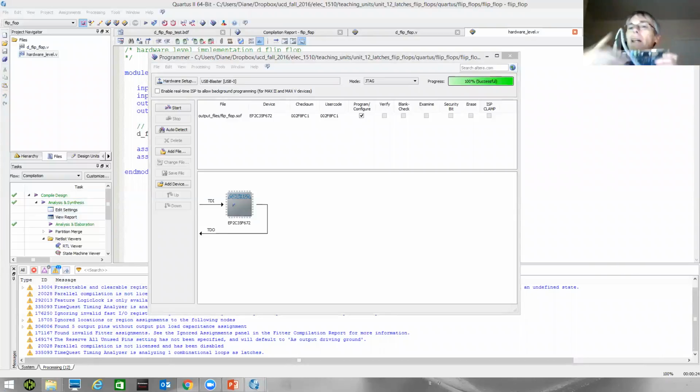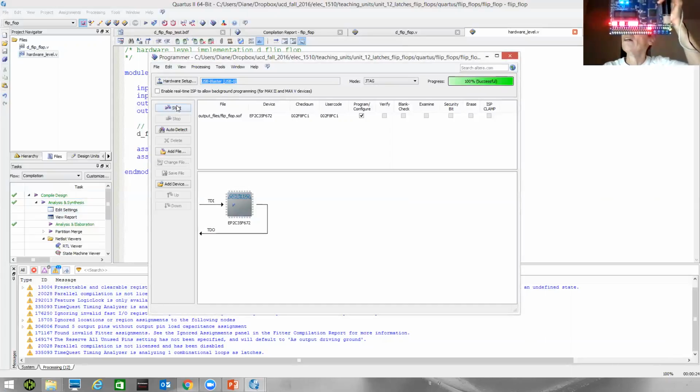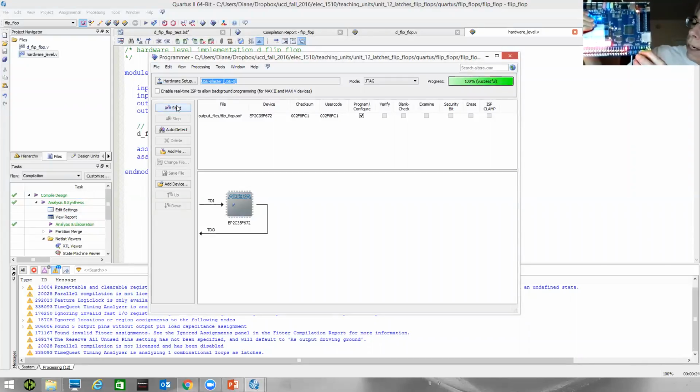I start the video back up. I turn the board off to erase the last program, and turn it back on. Go ahead and start the programmer. Now let's see what we've got on here. All of the green LED lights turn on. Remember, these are active low devices, so when the push buttons are not pressed, that will activate the green LED. When I press it, then key 1 is connected to green LED 1, and that turns it off. So active low: depressing, if you think of that as a 1, is going to turn it off. The 0 activates it.